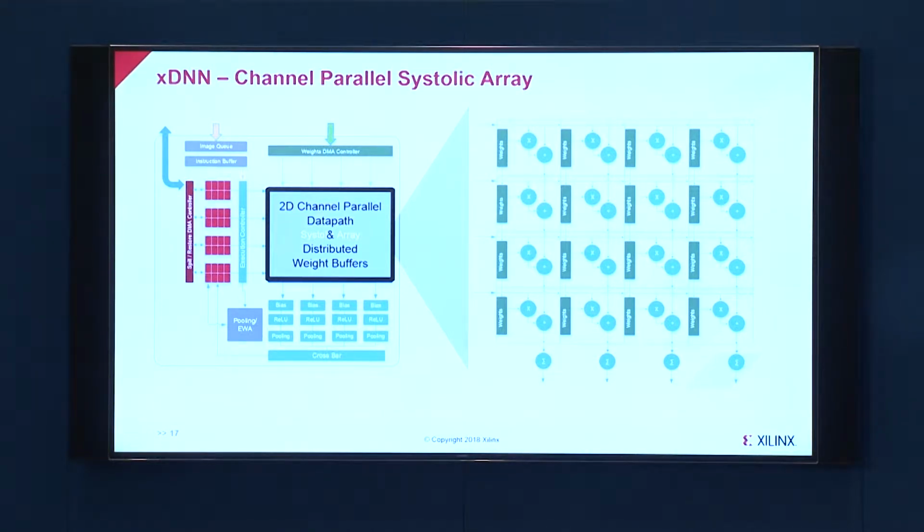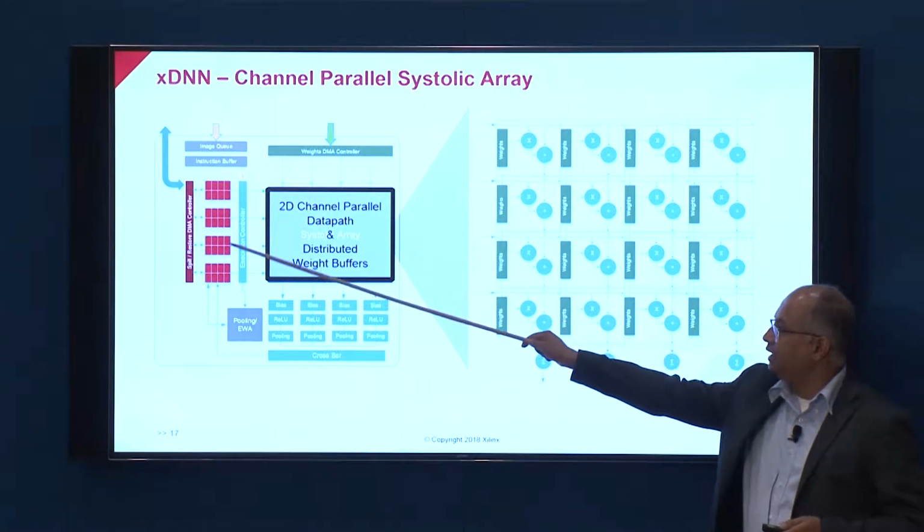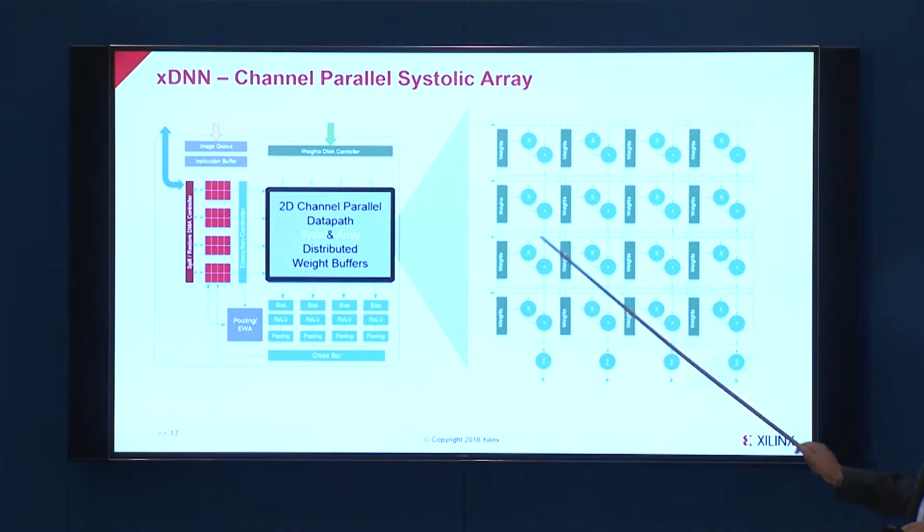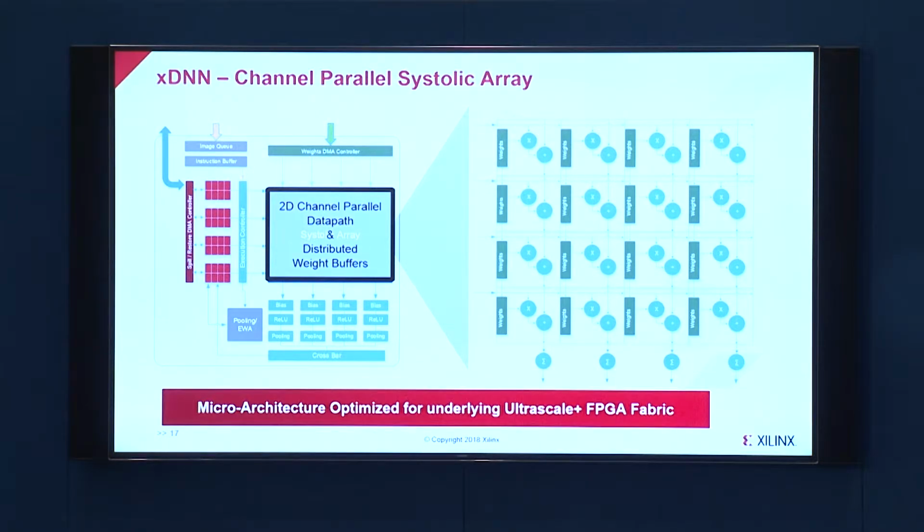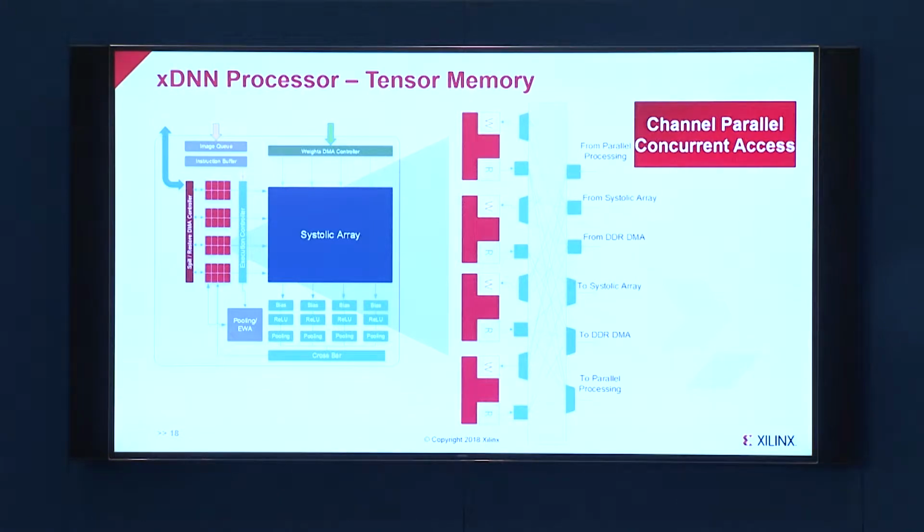So really, we have 3 levels of memory hierarchy. We basically come from DDR to this, and from this to the distributed RAM, right? So that is really the 3 levels of hierarchy we have. And to allow simultaneous execution of different blocks, there is this crossbar which provides you with a multi-ported memory, which is very specifically designed for this processor by looking at what access patterns are possible.